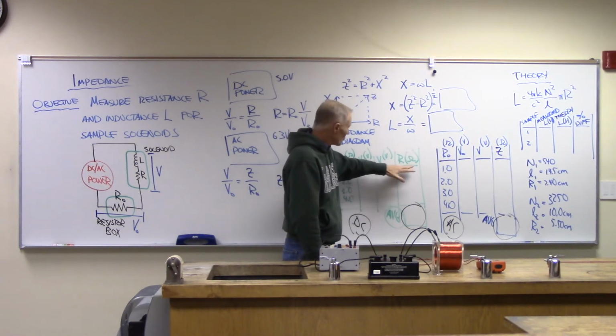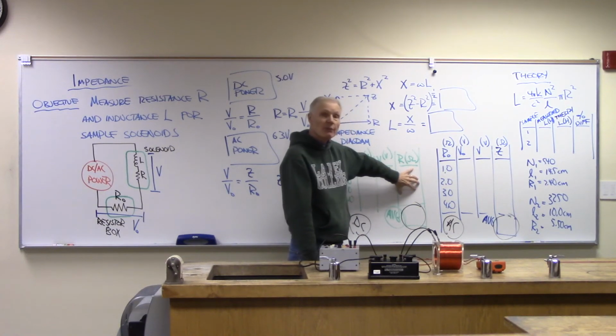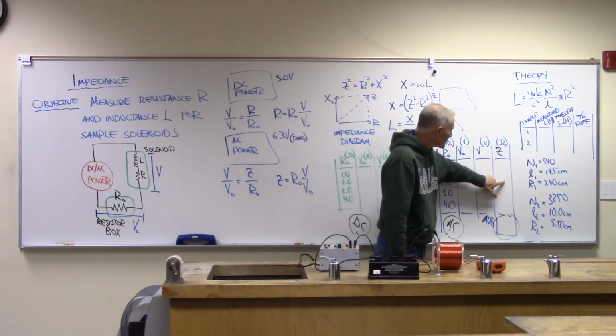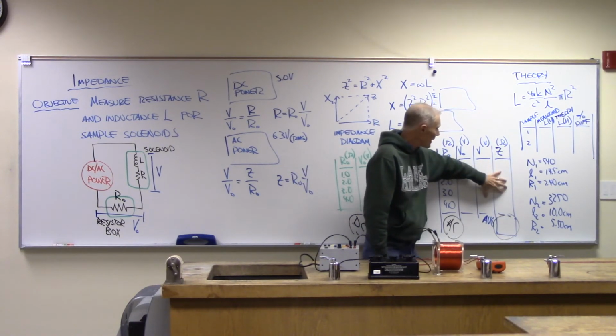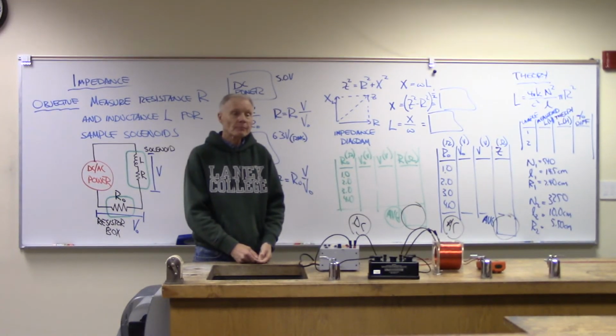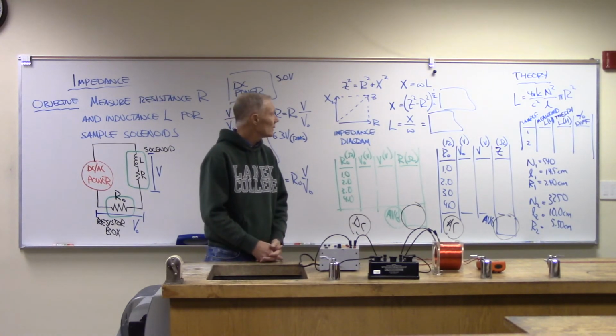One thing you want to watch for is the resistance measurements. These should be very similar. If they're not, go back and check. And then again, the impedance values, the 4 values we have here, we're going to do 4 runs for each of these, those should match up pretty well also. If they're not matching up, stop by and let's take a look at your numbers and see what's happening.